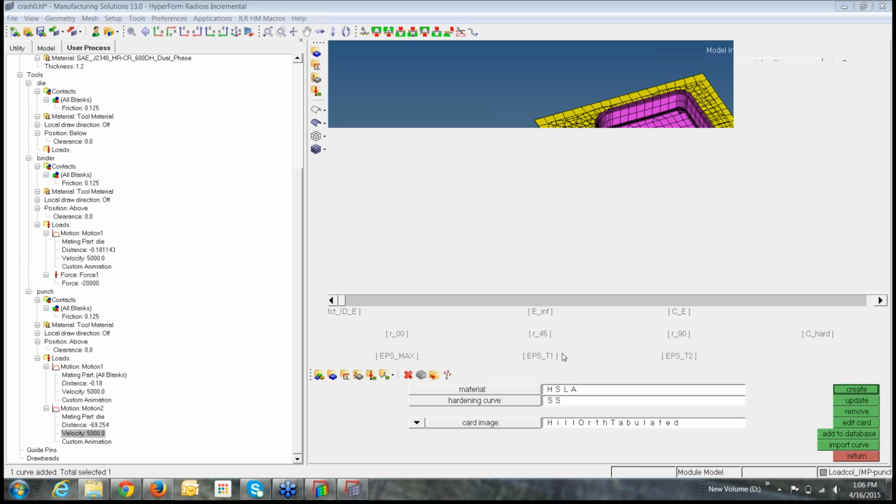Advanced mass scaling is an option wherein you don't have adaptivity in your elements. It automatically uses adapted size of elements. You need to mesh your blank with a size of 1 or anywhere ranging between 0.8 to 1.5 or 2 mm, if your model is in mm units.